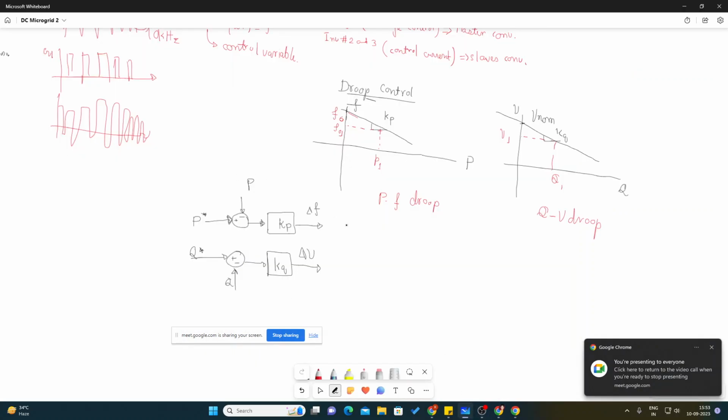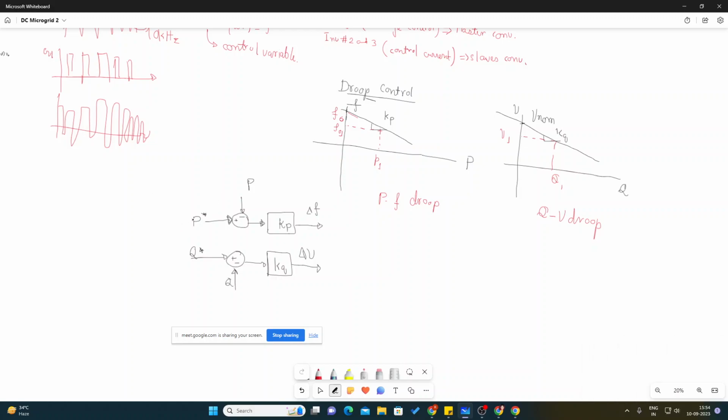Okay. So the variation is determined with this, so the P star cannot be anything. It has to be within a given range that it can supply, like P star should be within an interval P1 comma P2, and Q star should be within an interval, and then the choice of Kp and Kq. This will set it within the limits.